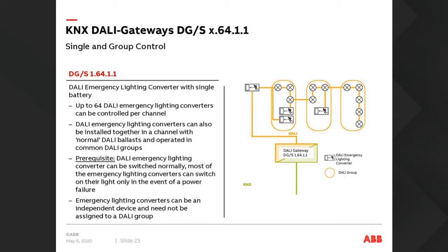One thing to be careful of, I know what some people do nowadays, is when there are no lamps on in the installation, let's turn off the power to all the ballasts. So as you see this system here wired, we are going to turn off the power to all of these ballasts. And of course, what happens with an emergency light when you kill its power? Well, of course, you're going to get the emergency fitting come on. So just be aware of that as well. Some people, I've seen that mistake made, where it's expensive then to go and get it rewired, and cause a bit of grief and time.